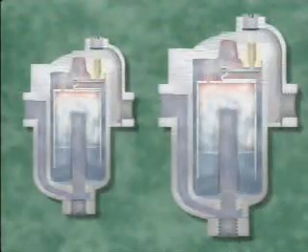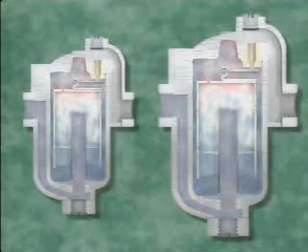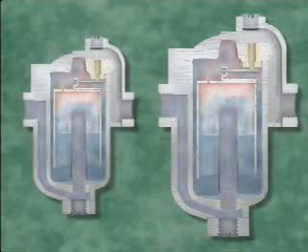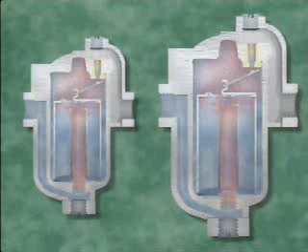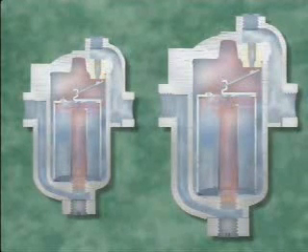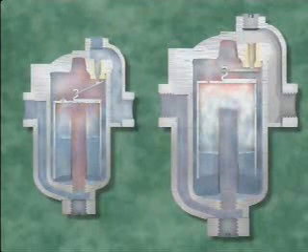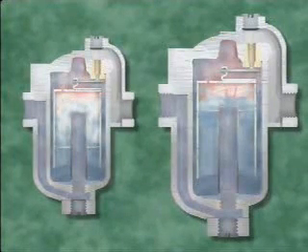If you must replace an old or damaged trap with a completely new one, be sure that the new trap is the right size for the installation. A trap that's too large remains closed for the same amount of time as a properly sized trap because closing time is based on the rate of condensate accumulation, which depends on how fast the steam is condensing, not on the size of the trap. But an oversized trap can discharge condensate faster, so it opens for a shorter length of time than a properly sized trap. Over the same time period, then, an oversized trap will open and close more frequently and consequently wear out faster than a properly sized one.